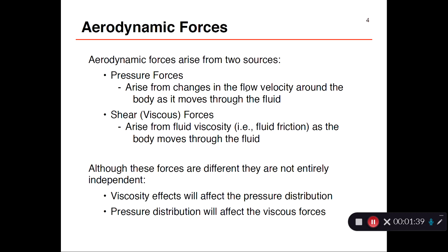When the velocity increases, pressure decreases, and vice versa. In compressible flow, we have a compressible energy equation. When the velocity goes up, temperature goes down, and vice versa. When the temperature goes down, from isentropic flow considerations, pressure also goes down, and vice versa.